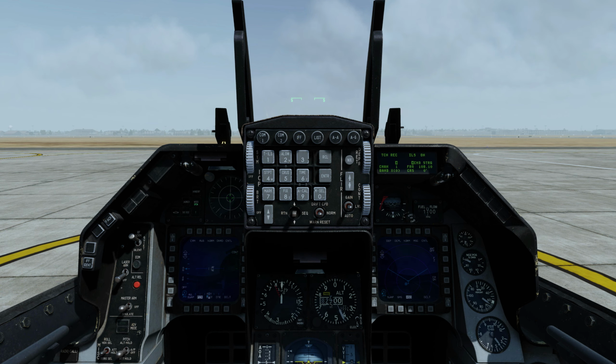To enter an ILS frequency, input the desired frequency and press enter. And to enter the ILS course, dobber down with DCS to move the scratch pad to the course line, input the course and press enter.